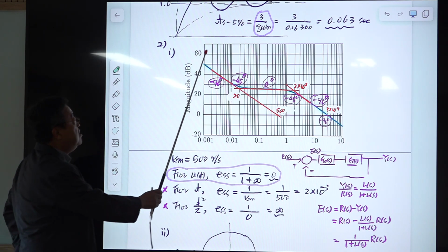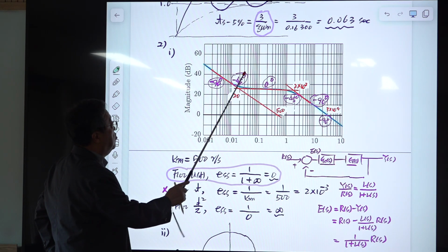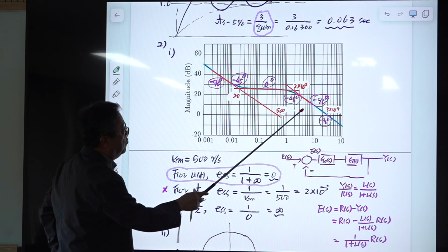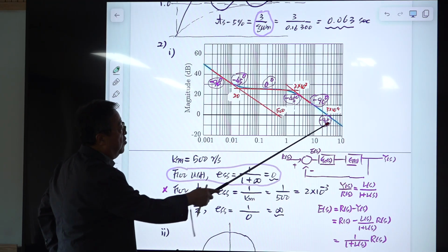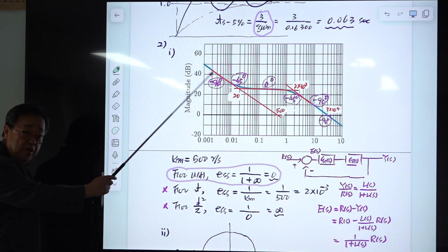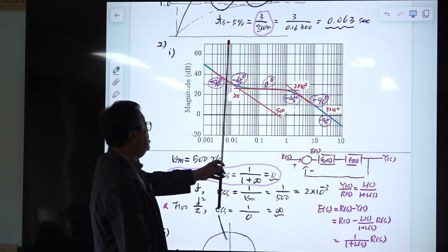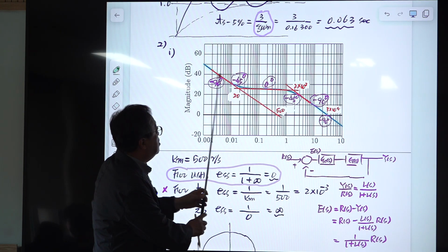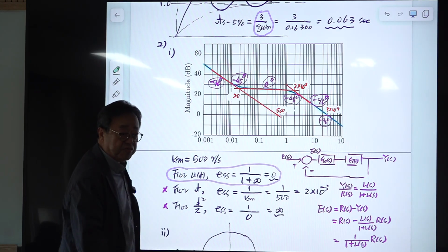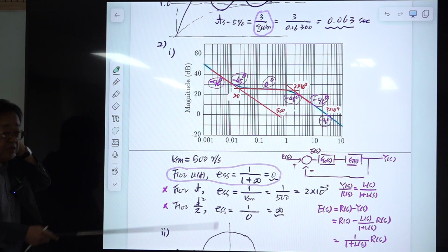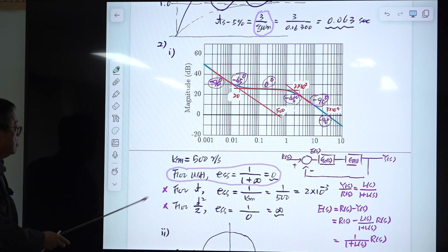The phase is approximately -45 degrees, 0 degrees, -90 degrees, -45 degrees, and so on, and the final phase is -90 degrees. Of course this is an approximation, but this is good engineering practice. At the corner frequencies, the phase is something in between, so -45. Use this number. It is a good approximation. Why use other numbers? This is the best number to select, right?